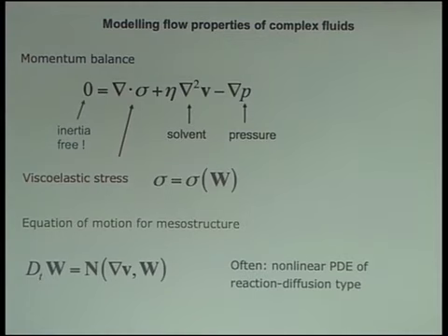And to someone from the conventional fluid mechanics background, you may then think all the interesting stuff's been thrown away because, of course, it's the nonlinearity of that term, the v dot grad v term, that gives us, for example, transitions to inertial turbulence. But the point is that in these complex fluids, we can see a whole host of flow-induced transitions instead because of the inherent nonlinearity of these additional equations here that tell us about the viscoelastic stress. So in other words, the nonlinear dynamics of the way that polymer chains or liquid crystalline molecules respond to an applied flow.